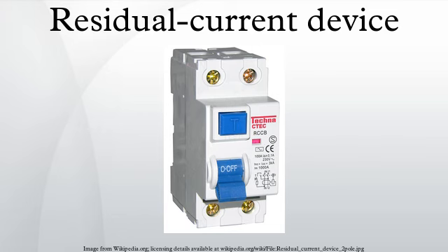The IEC 61008 and IEC 61009 standards impose the use of a 0.5 microseconds/100 kHz damped oscillator wave to test the ability of residual current protection devices to withstand operational discharges with a peak current equal to 200 A. With regard to atmospheric discharges, IEC 61008 and 61009 standards establish the 8/20 microsecond surge current test with 3 kA peak current but limit the requirement to RCDs classified as selective.